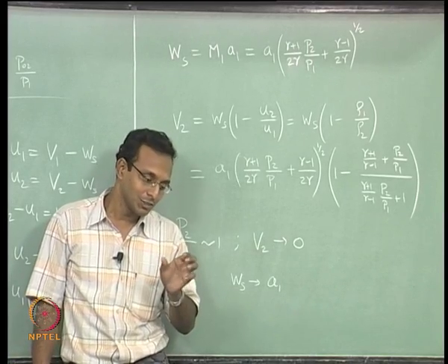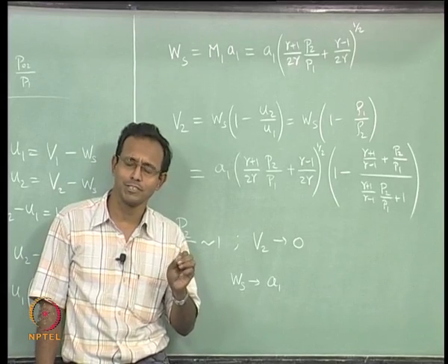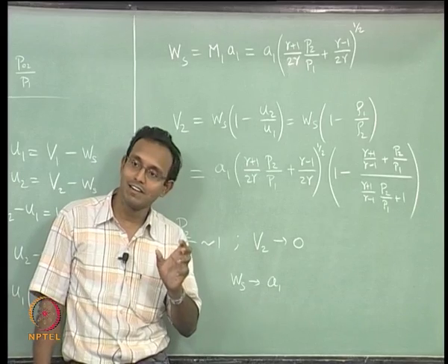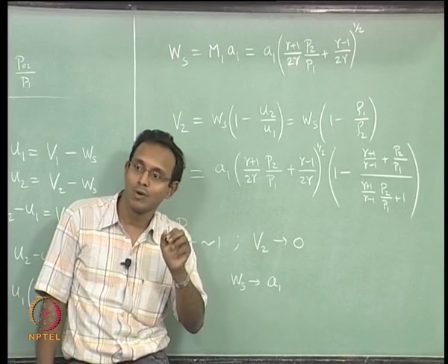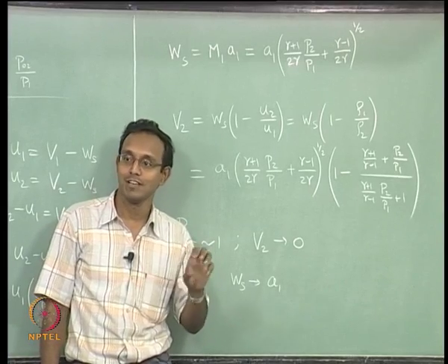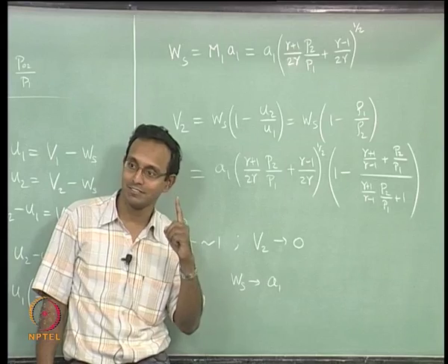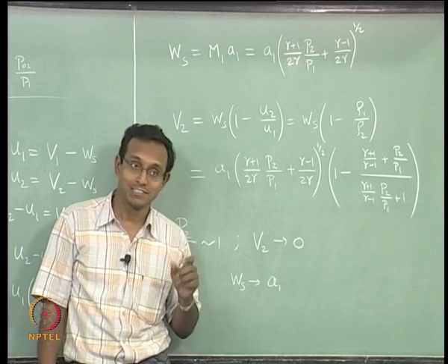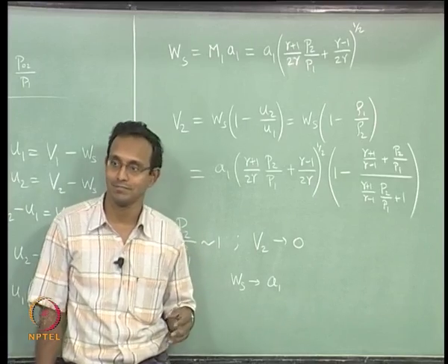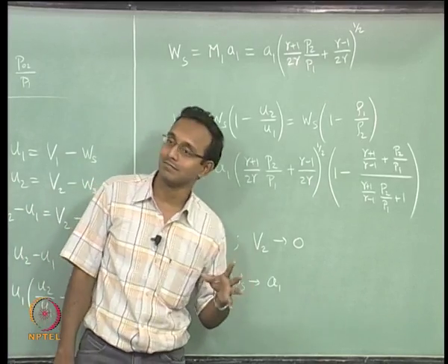When the compression waves come together, they will tend to overlap one on top of the other and become one strong wave. If there are some 10 waves, they all will coalesce to form one strong wave. It will still be that thin shock wave as far as our gas dynamics assumption is concerned. It will be reasonably thin.